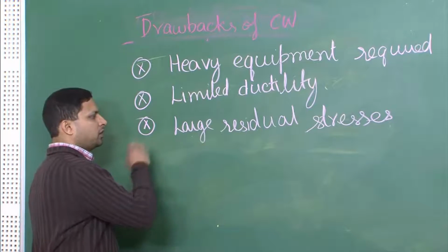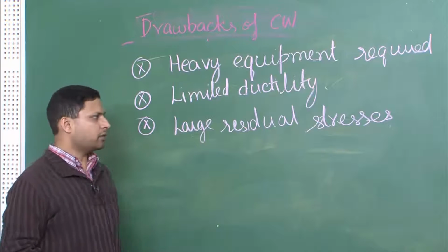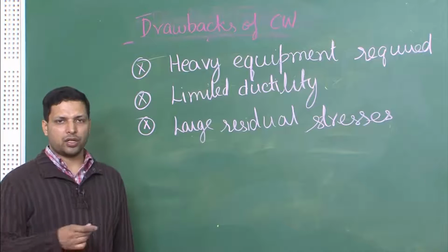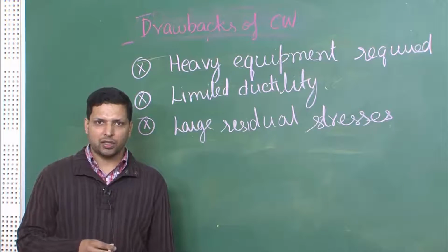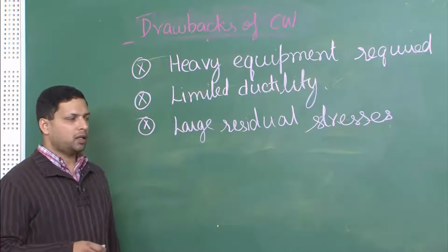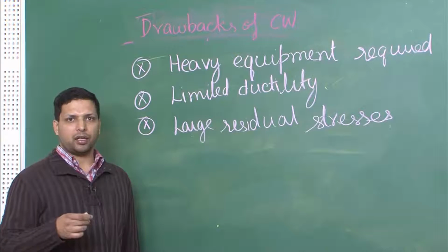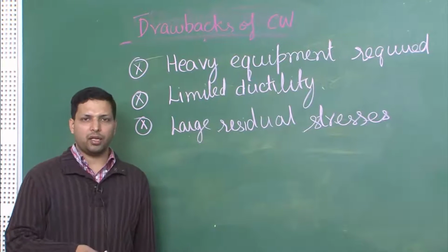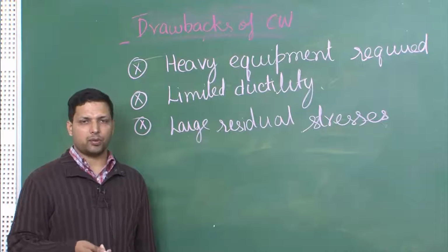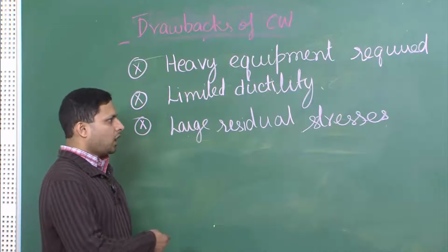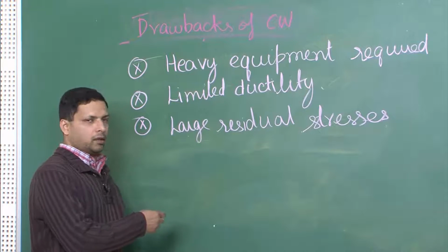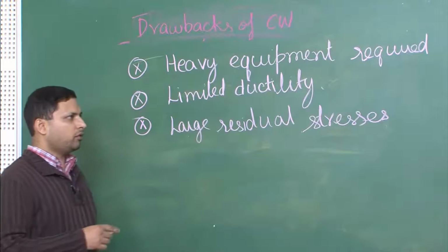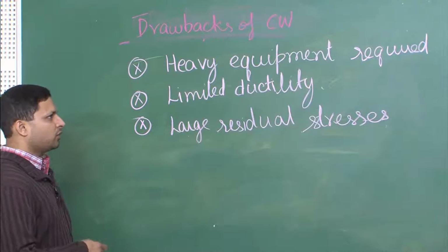So, another important disadvantage is large residual stresses, and as I said earlier, when you have a component manufactured using cold work and it has very large residual stresses, it implies that those components can generate defects very easily, and may fail very quickly or at a much lower frequency under fatigue stresses. So, this reduces or limits the life cycle of a component. That is one very big disadvantage when we are using cold work.